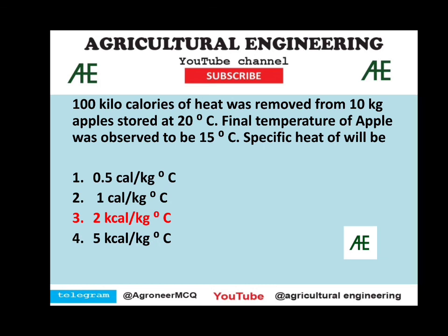100 kilocalories of heat was removed from 10 kg apple stored at 20 degrees Celsius. Final temperature of apple was observed to be 15 degrees Celsius. Specific heat of apple will be. So for finding out specific heat, we have to find the formula, which is heat transfer is equal to m cp delta T, where m is mass of product, which is 10 kg, cp is specific heat, which we have to find, and delta T is temperature difference.